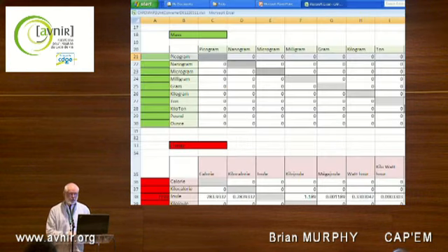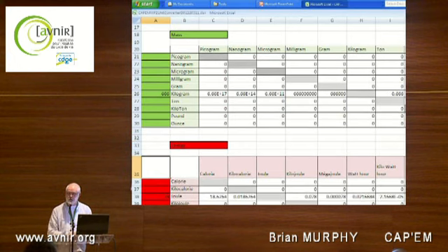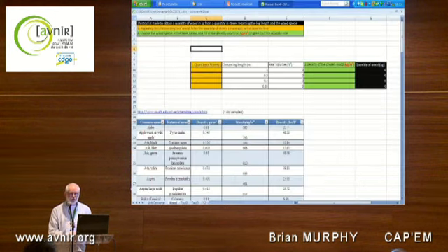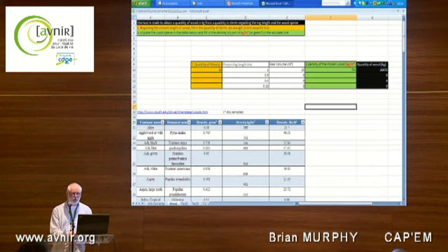And along the way, gathering information from manufacturers' literature, inevitably the information's in the wrong format. So type in the green box on the left-hand side and you get all of the variety of outputs immediately. So it's very easy to get the information that you need in order to carry out your LCAs. Equally for energy. And another little tool along the way, the volumes and density and quantity of timber. It comes in a whole variety of sizes. Just type in the quantity, type in the density from the table below for all of the species that we are aware of, and you'll get your information.